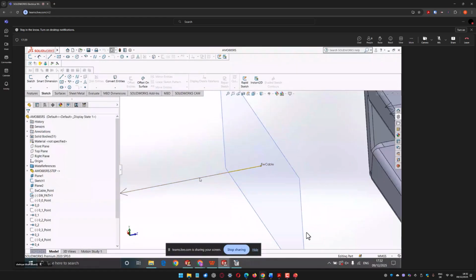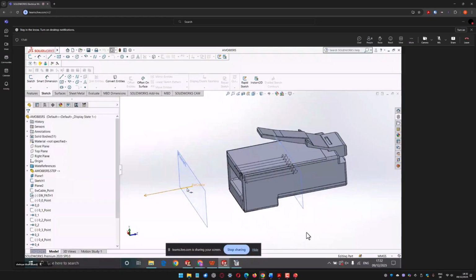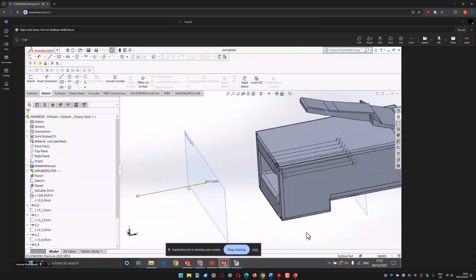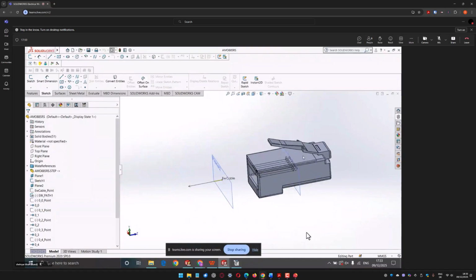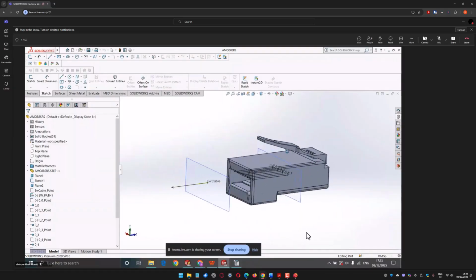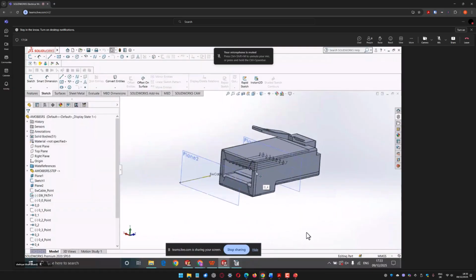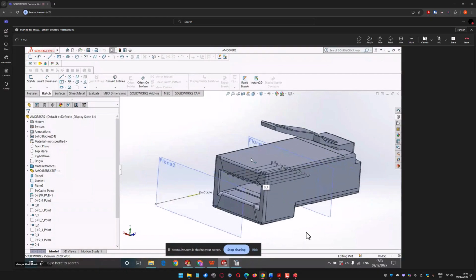So this is also important, because SOLIDWORKS somehow doesn't pick the connection point by itself. So you have to at least tell it from where to start and how to do it. So these are the basics which we set up for our connector, which is the main part before starting anything.